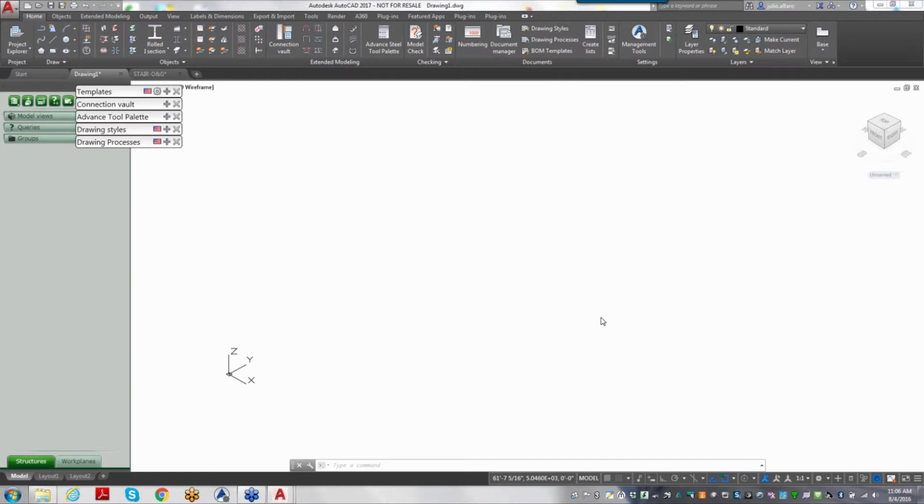an engineer or an architect doing his design inside of Revit, and then doing drawings or whatever. But Revit will not give you detailed drawings like Advanced Steel will. In other words, it'll give you center-to-center dimensions for beams, columns, and so forth, but it will not give you the exact cut of copes, holes, tags for beams, and so forth. That is where Advanced Steel comes in. You can get a model straight from Revit, import it into Advanced Steel, and then start doing your details, because the model will be one-to-one from Revit.